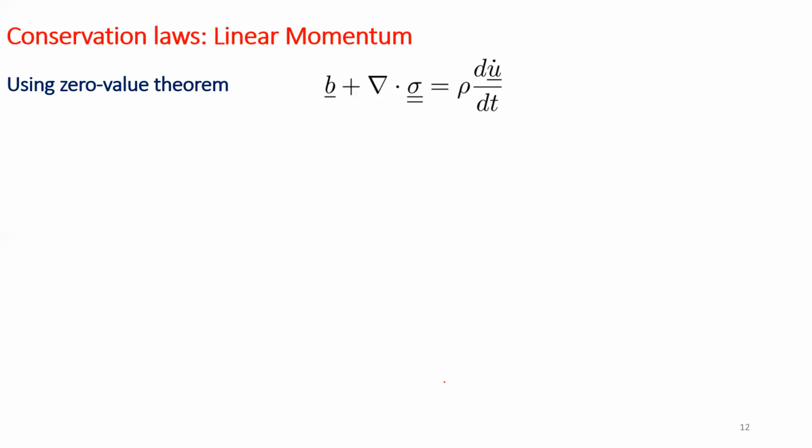In other words, one can call it the linear momentum equation as well, because that is what we started with, and we have included the elastic nature of the object. Assume that the body does not deform. If the body does not deform, there is no strain and no stress. So essentially, what you have is F equals ma per unit volume. That's what we are saying here.